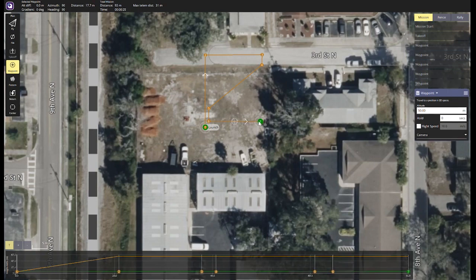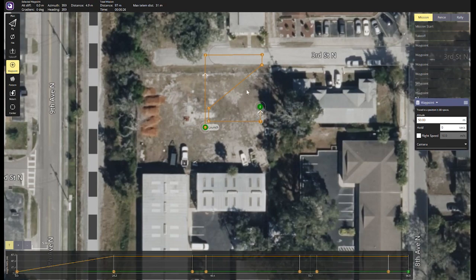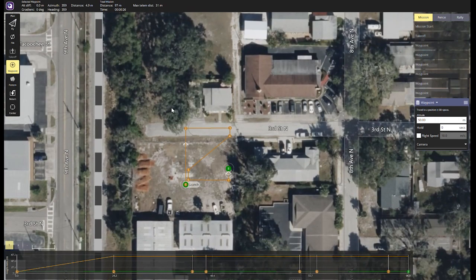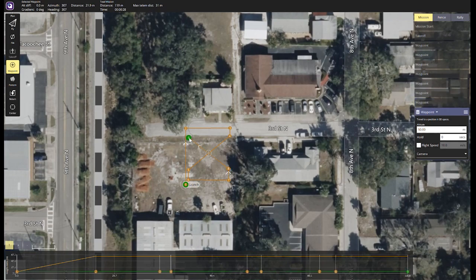Begin writing your initialization by creating a clean figure 8 or an hourglass, making certain to not write any acute angles throughout your mission. Angles under 90 degrees will cause inconsistencies in smooth flight and will negatively affect the data that you ultimately collect. For this example, the initialization has been accomplished using 9 waypoints.